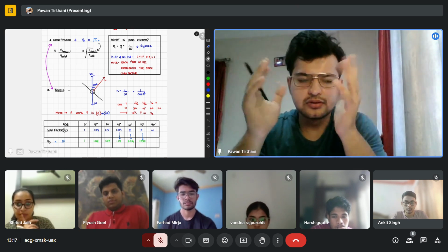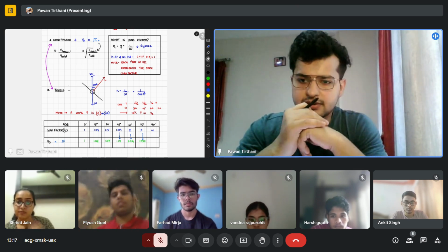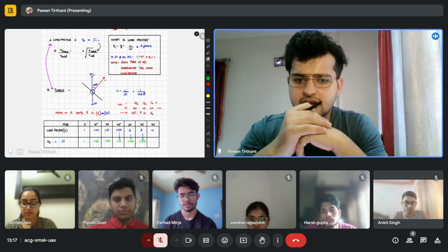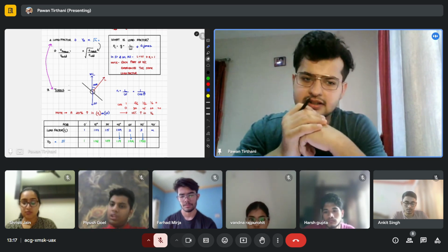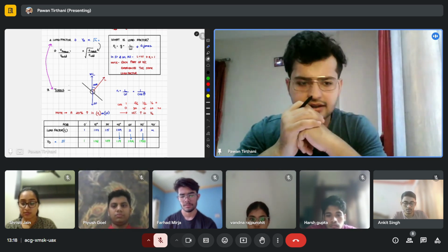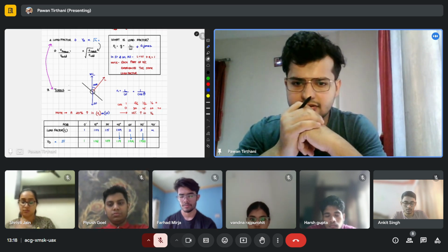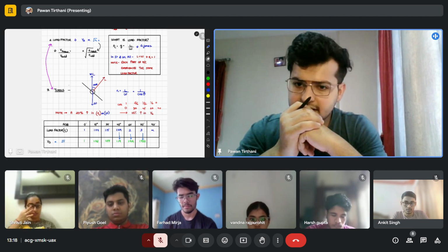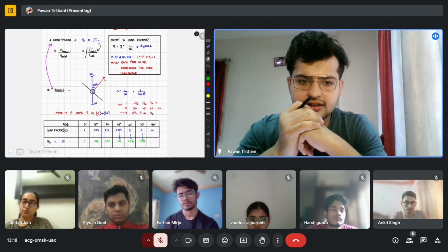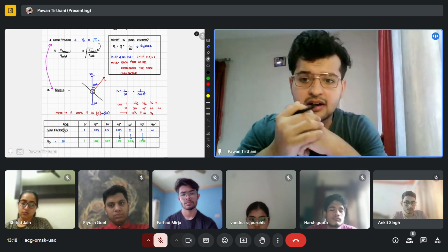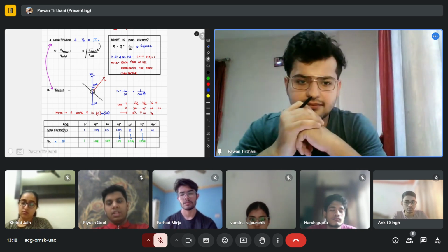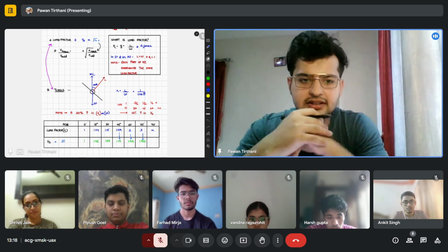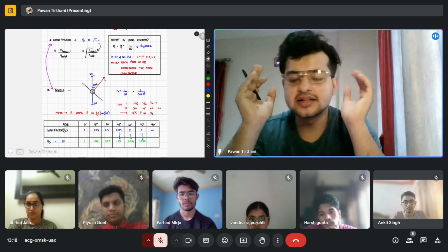Easy. I want you all to close your eyes. Imagine the lift equation. Lift is equals to half rho v squared CLS. But on the left side of this equation, you also have weight is equals to lift is equal to half rho v squared CLS. Now I've written very heavy passengers inside my aircraft. The weight increases. Hence, the lift that I require to build also increases. But my airframe remains the same. The surface area of the wing is the same. The coefficient of lift or the angle of attack that I have is the same. The density is the same. Half remains the same. What can I increase? The speed. So at CL max, if I have to increase the lift at CL max, my stall speed will increase. Do you guys understand this?